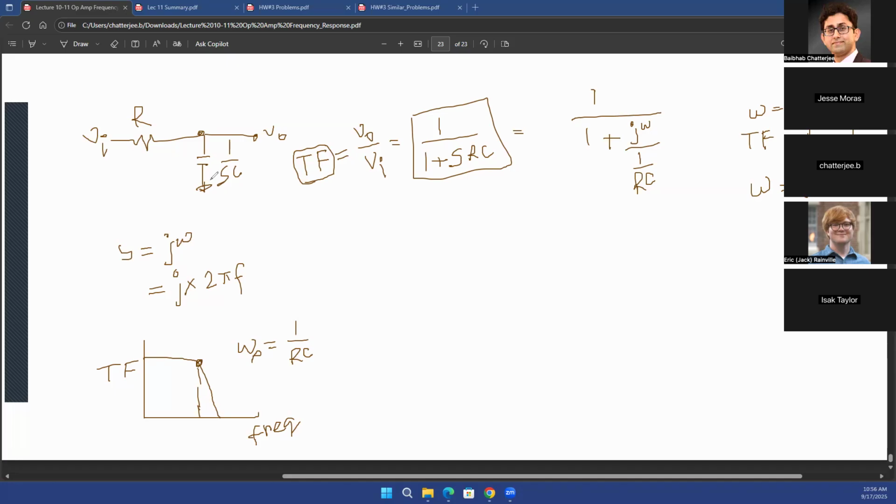At high frequency, for example, radio frequency, microwave frequencies, you may have heard of millimeter wave, let's say 30 gigahertz to 300 gigahertz frequencies. In that case, what happens is that the capacitor is becoming a short. That actually creates a problem in your circuit, because whenever you have a short, the voltage drop across the short becomes 0, right? So you don't even get any voltage. That's the problem. So that's why in RF, millimeter wave, or microwave frequencies, capacitors become the biggest source of non-ideality.